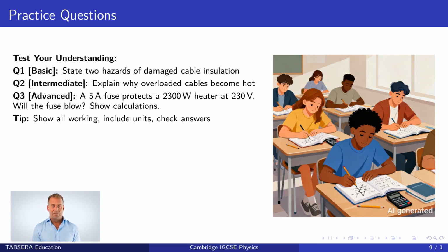Question 3 is advanced. The question is, a 5 ampere fuse protects a 2,300 watt heater at 230 volts. Will the fuse blow? Show calculations. This tests your analytical skills using current and power relationships. For all questions, remember to show your working clearly, include units in every step, and check your answers make physical sense.